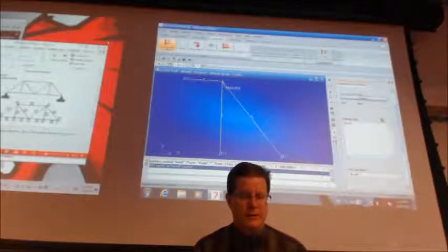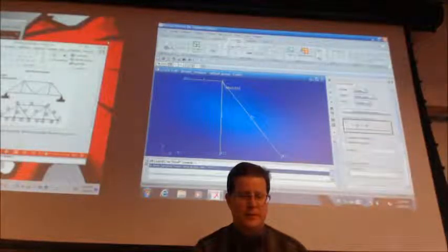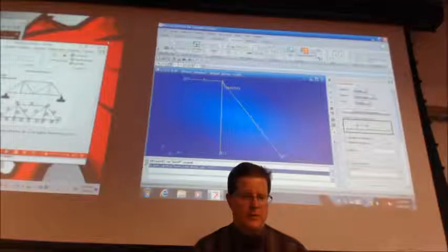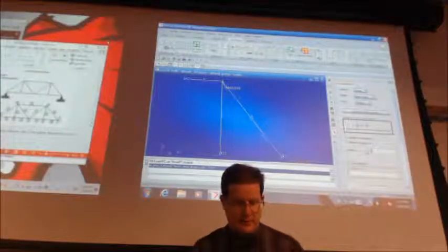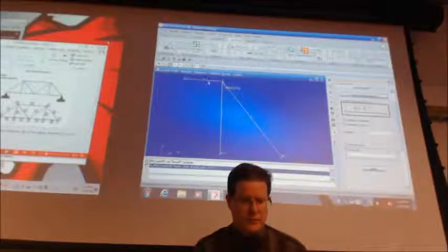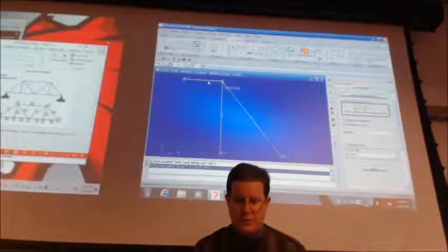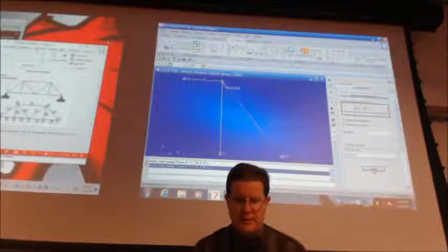Okay. So let's see, we did our constraints and our force. So now we can move on to meshing. And we're going to do number of elements is 1. So curve list, apply, 2, apply, 3, apply.